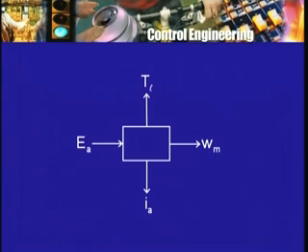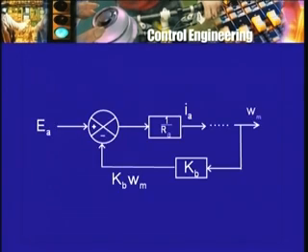So I will show a block which is going to be like our difference device. The symbol for that is not really a rectangle, but a circle with the four quadrants shown in the traditional way. To one of the quadrants I will mark a plus, and give EA as the input. To the other quadrant I will mark a minus, and give an output coming from omega m. I am just showing that signal omega m as an arrow coming out.